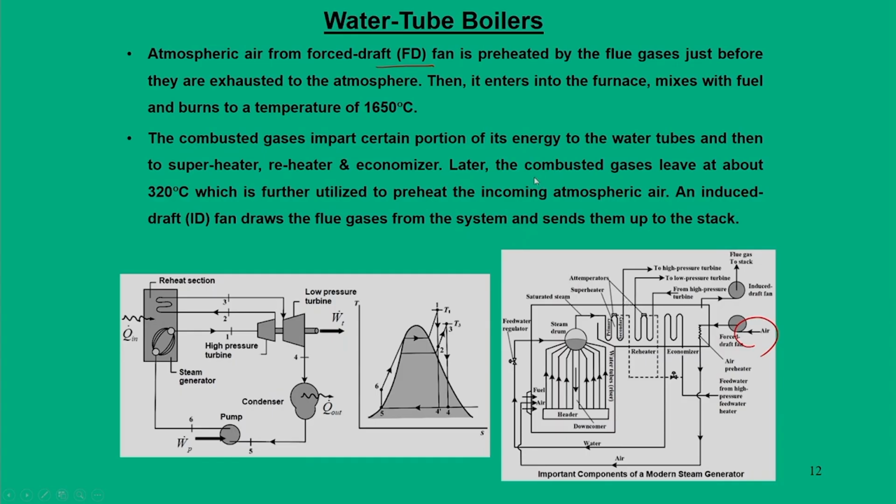Again, the combusted gas has to leave. Once the combustion process is over, that exhaust from the steam has to leave through the stack at around 320 degrees centigrade. That is the reason we also require the induced draft fans, which draw away the unwanted flue gases.